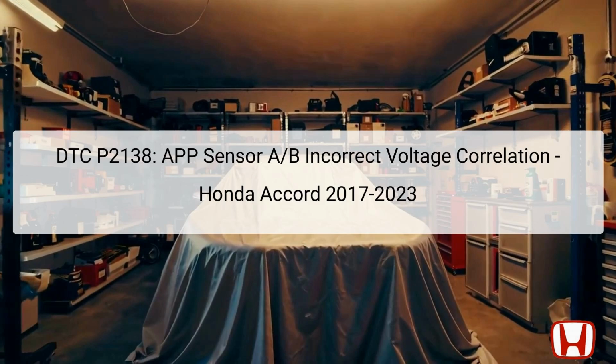The Diagnostic Trouble Code, DTC P2138, indicates an issue with the Accelerator Pedal Position, APP, sensor A and B, specifically an incorrect voltage correlation between these two sensors. The vehicle uses APP sensors to determine how far the accelerator pedal is pressed, sending this information to the Powertrain Control Module, PCM, to regulate engine performance.